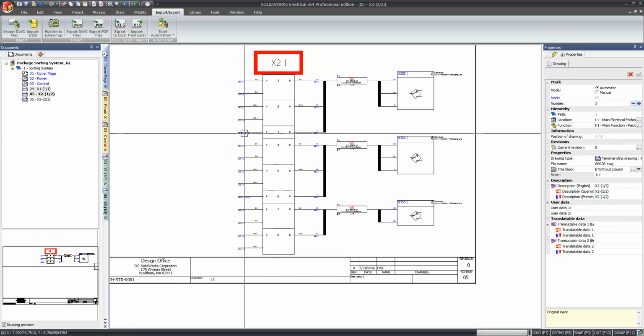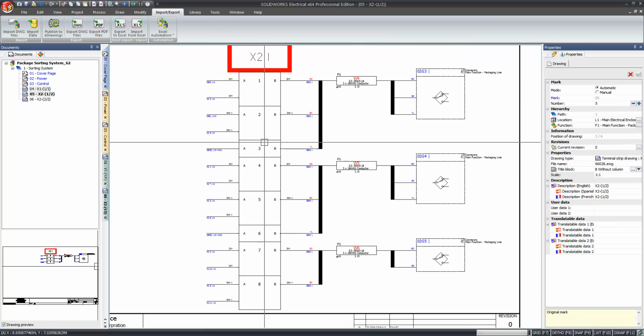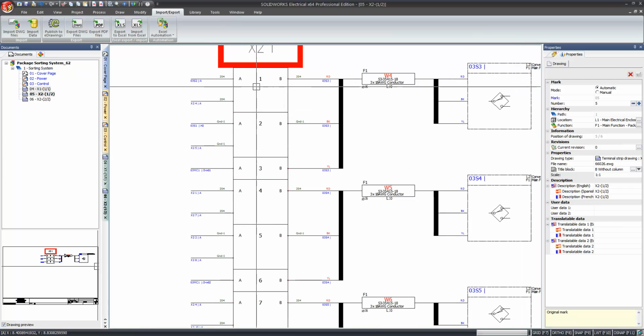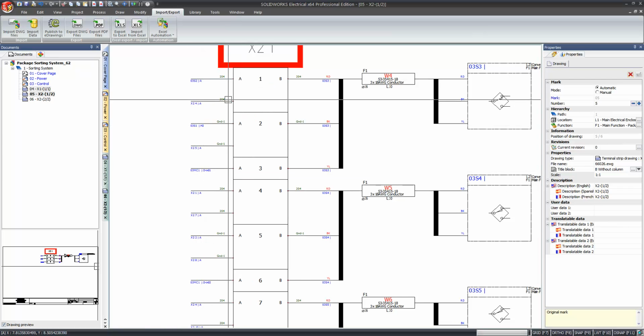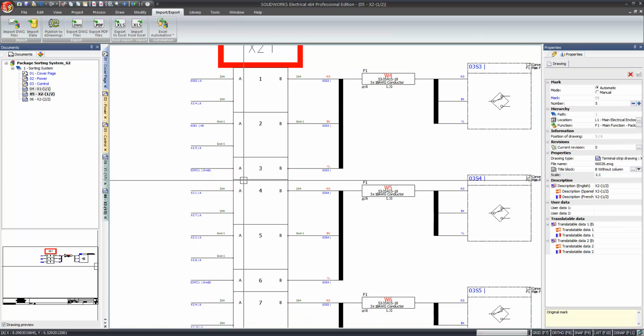And finally, you can see in this terminal strip number 2, notice how terminals 1 and 2 are large. They have 2 wires going in each one. So what we have is the power wire coming in, then we have this jumper going out to connect from terminal 1 to terminal 4. Then we connect from terminal 4 to terminal 7. So it's kind of messy.